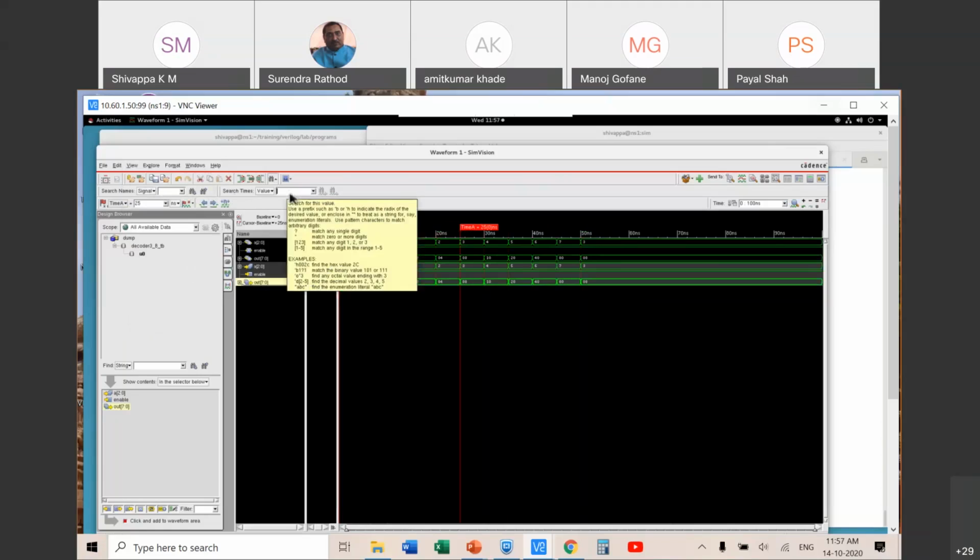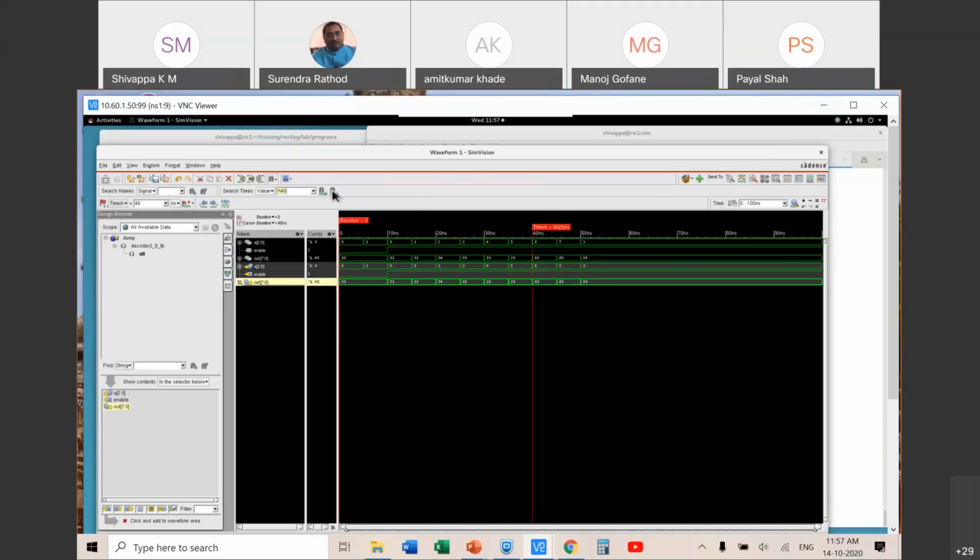And then you can search a signal. You can search for a value. Let us say 40, right? It should take you to the place where this value is 40. Let me see. Yeah. See this? So it's all GUI. You go and then explore, and it displays what signals are there in each scope, right? So this bare minimum info is good enough for you at this point in time.